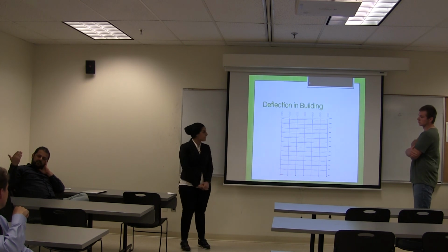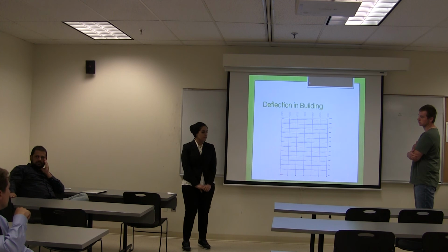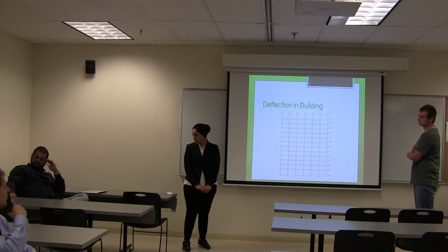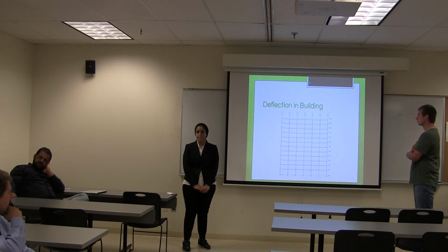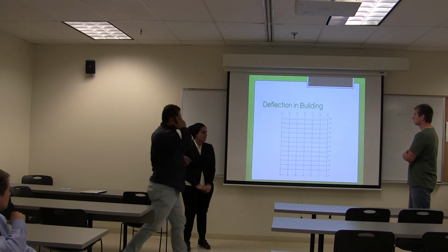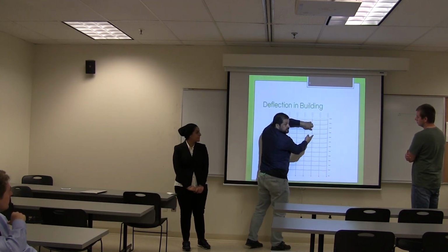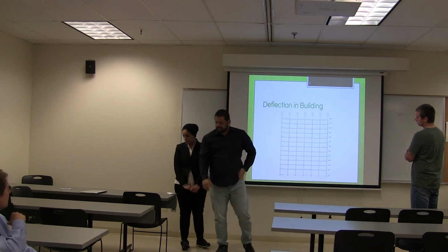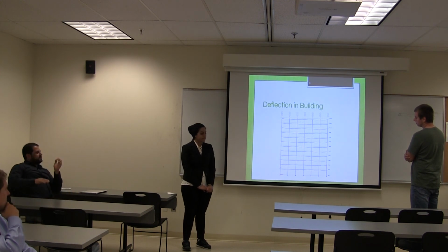But you tell them, okay, if you are talking about deflection of the columns, that's accumulative, right? Because each floor is stretching, each column of each floor makes it a little more sunken from the next one. That's cumulative at the top. Because look at that column. This is the axial deflection in this column, from here to here. Any other questions? Okay guys, good job.